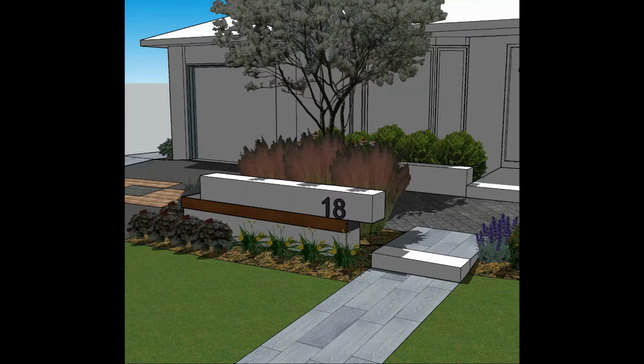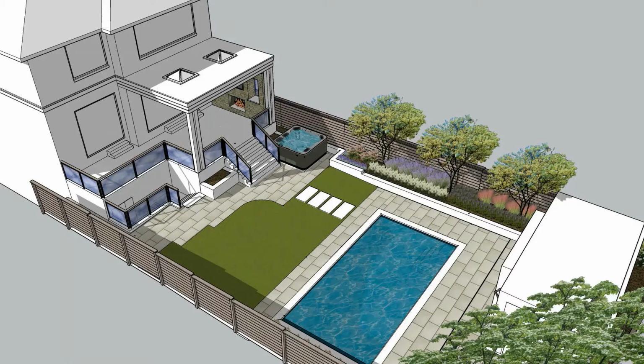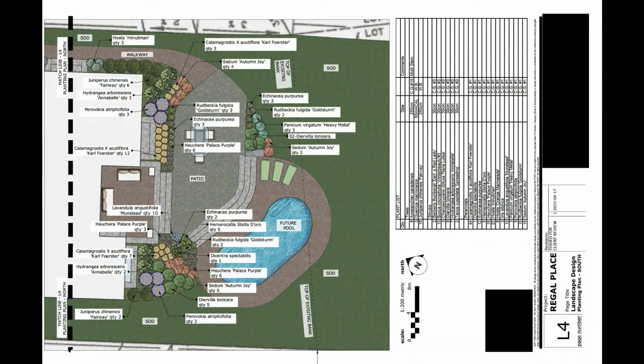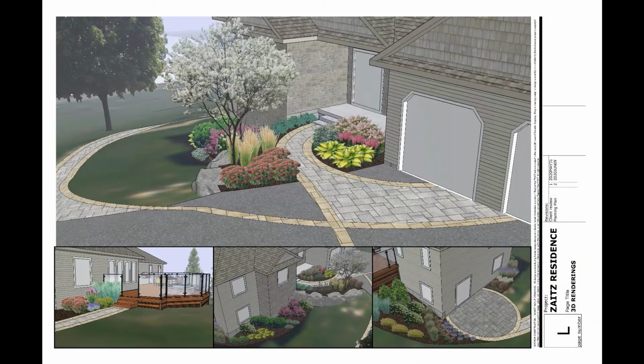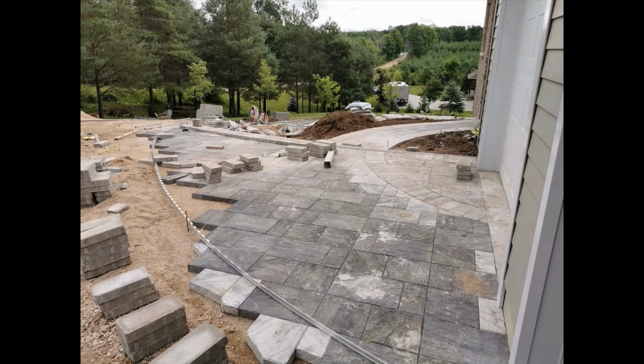So if I'm just doing a quick permit drawing and figuring out where the trees are, I might just load it into DraftSite, create a quick 2D plan, and be finished with it. But a lot of the times, if I'm doing a full landscape design, I'm loading it into SketchUp. I'm really starting to work with that 3D information, preparing conceptual grading plans, conceptual landscape designs that actually work in the third dimension, then presenting that to the client, and then you're starting to build detailed construction drawings that I can hand off to a contractor or crew to develop.